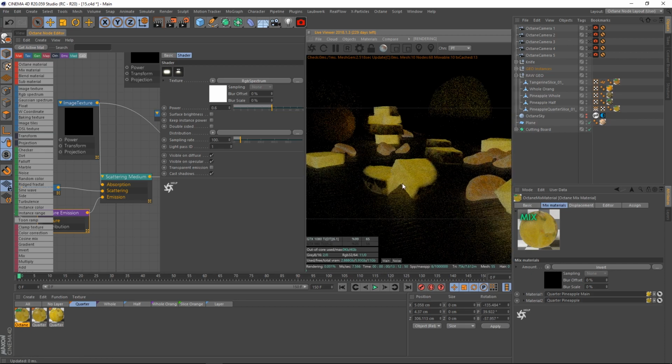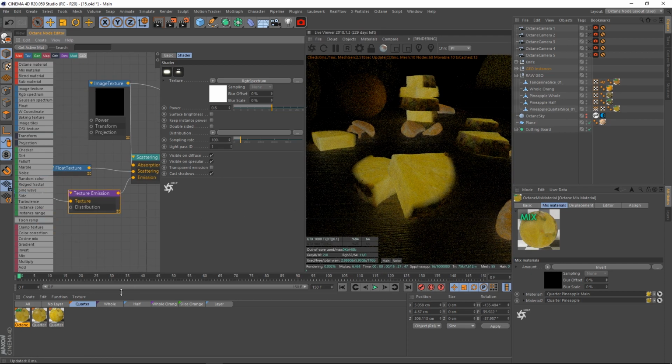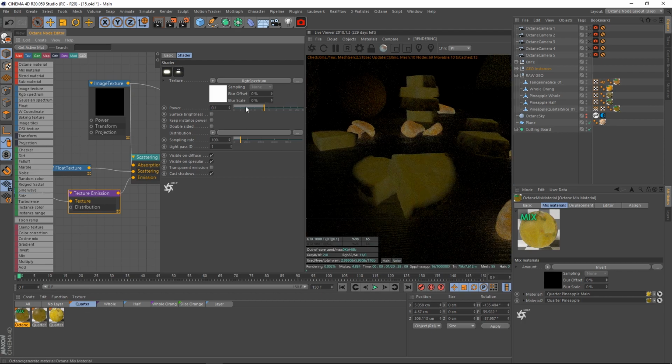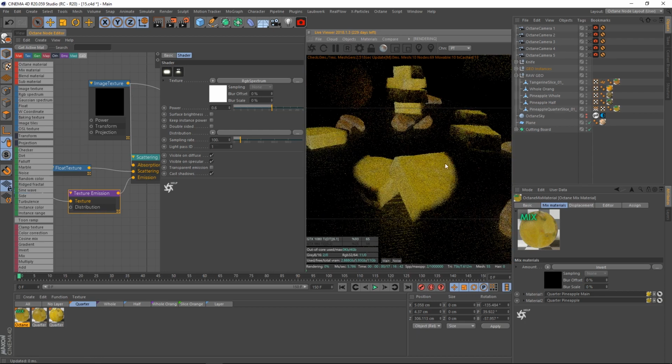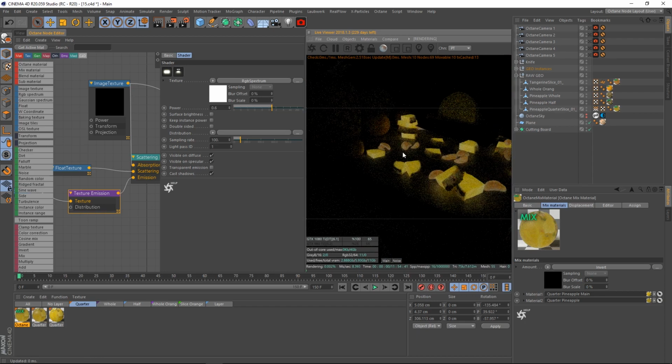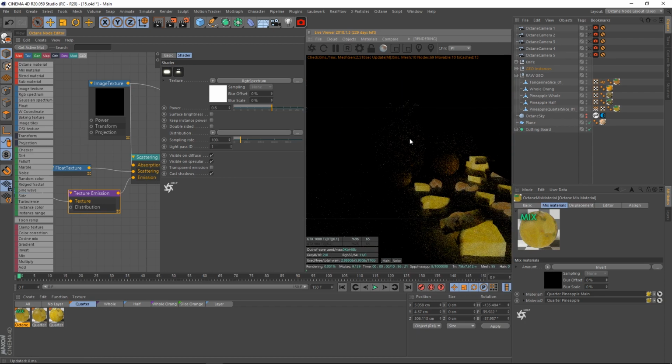You'd have to turn down the brightness on these. And that can easily be done just by selecting the material, going to the texture emission, and dropping it down. Maybe a value of 0.1, or in this case, maybe 0 if you want it to be really dark. But again, these are going to have to be altered based off of that. So that is a drawback. They're not 100% physically accurate in that sense. So that does kind of come down to that.